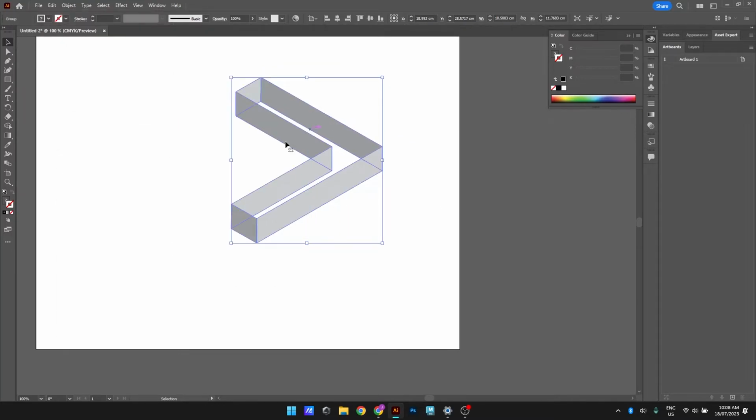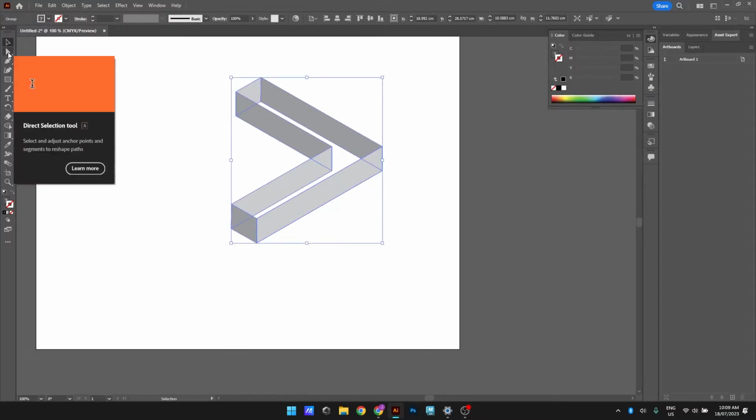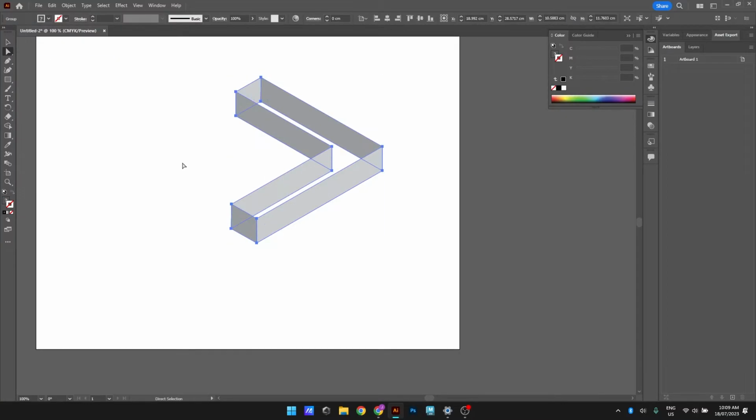What that allows us to do now is to delete any walls that we don't want. So all of these are now separate faces. But to select those faces, we need to use the white select tool. So I'm going to select the white tool, click on the background to deselect, and at the moment I'm just going to delete this wall, and I'm going to click on this wall and delete that as well. And now we have a hollow appearance, but we can't see the floor.